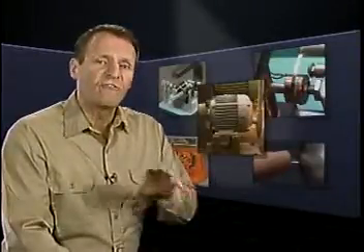An AC motor operates because of the interaction between the magnetic fields of its rotor and its stator. In most AC motors, alternating current is supplied to the stator windings. The current flow causes the magnetic fields around the stator windings to increase, decrease, and change polarity. Let's look at an example to see how the magnetic fields of the rotor and the stator interact in a